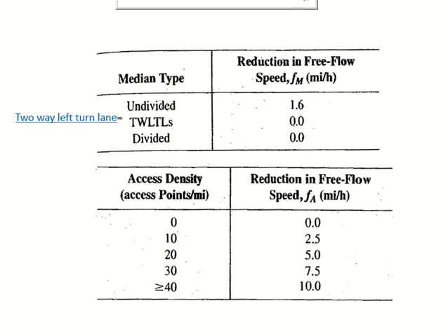So capacity and free flow speed are calculated for ideal conditions. Once you find them, you can apply some adjustment factors if the ideal conditions are not met. These conditions are related to weather, driver familiarity, incident, and work zone. Work zone has some calculations; we have seen it last time.